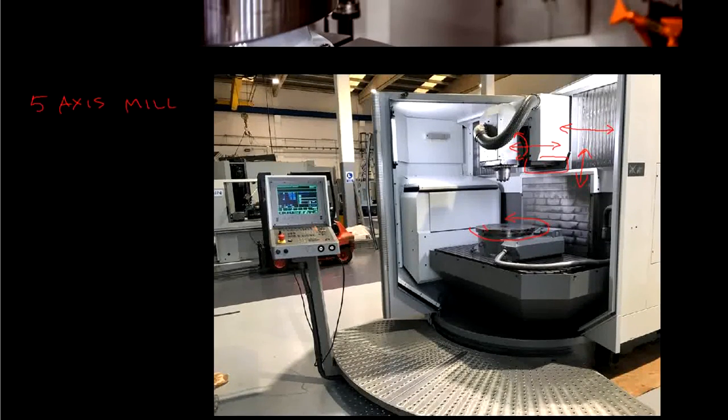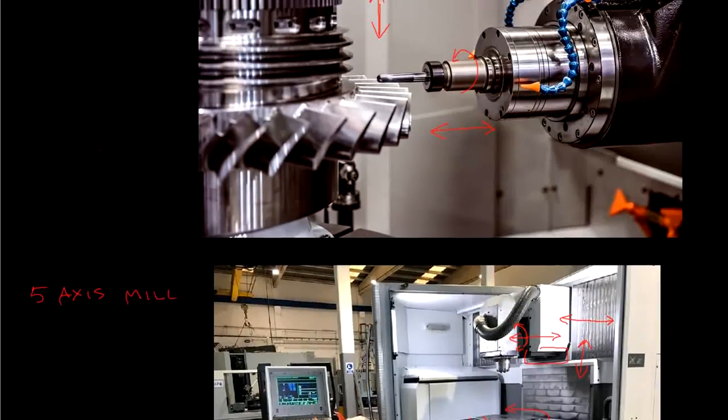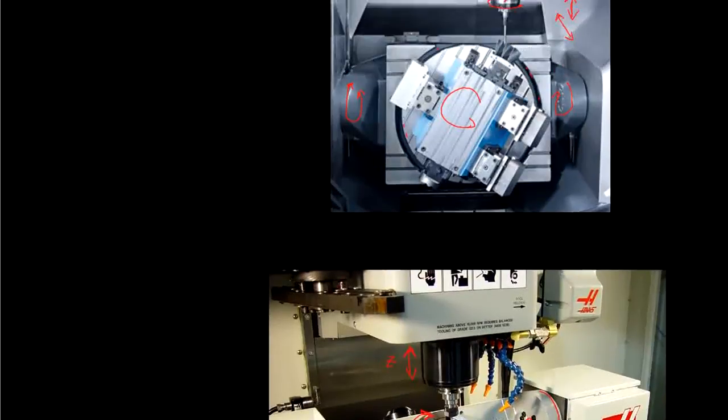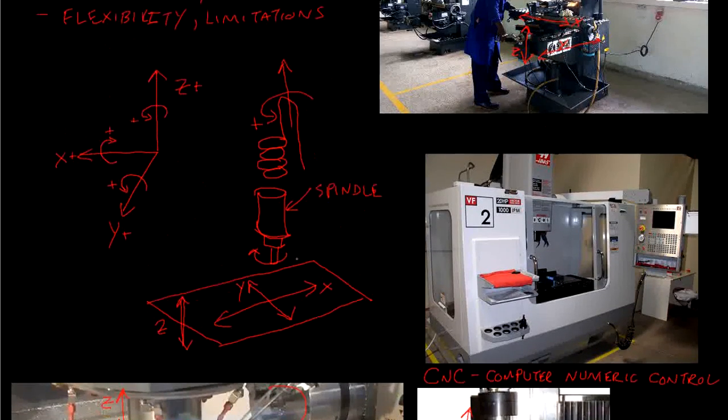So, just highlighting a recap of what we've gone through here. We just went through the flexibility of these machines. Another important part is that the cutter is rotating and the part is generally fed into the cutter, whereas in a lathe, in a turning operation, the cutter would be stationary and the part would rotate into the cutter.